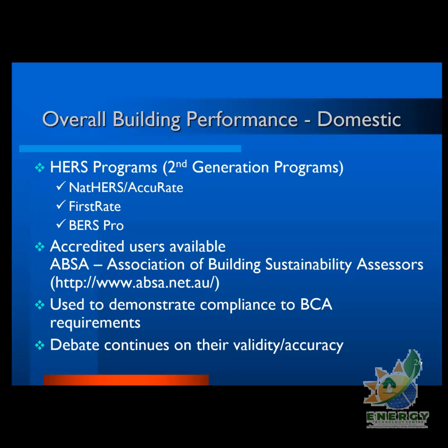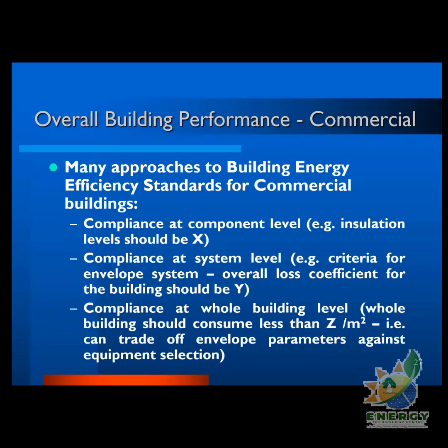Now, there are many approaches to building energy efficiency standards for commercial buildings. In fact, if you want to determine the building energy efficiency standard, you can specify this performance in terms of component level, that the insulation should be X square meter Kelvin per watt in terms of maybe R values.